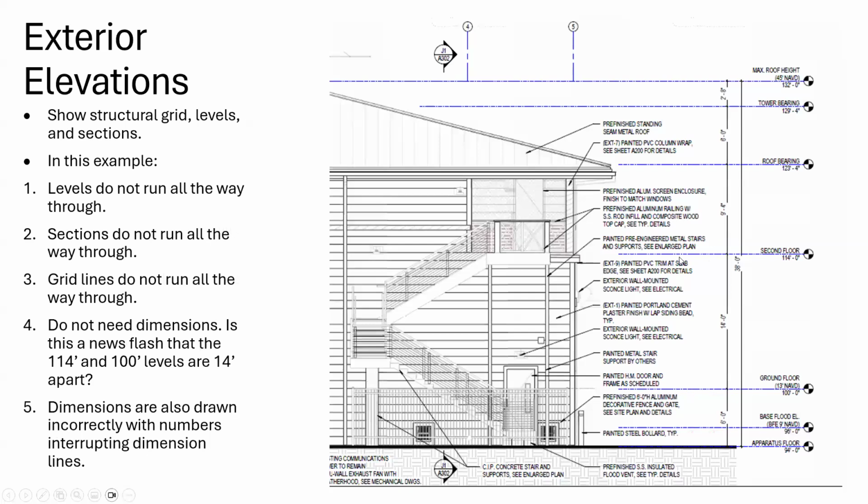You'll notice they use color for some of these things. I think Tim's a fan of using color for the grids. And I think Tim actually is going to teach you how to use color for the dimensions, which I'm not so sure about. They did their dimensions wrong. The dimension number should not stop the dimension line. So whoever did this was not a very experienced draftsperson because they set up their dimensions wrong. But it's a nice set of plans.